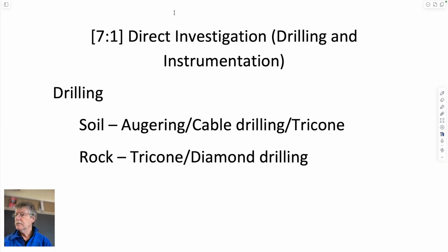They're preceded maybe by knowledge that you can get from what other people have applied at that site. But direct investigation would be digging trial pits, drilling holes in soil and drilling holes in rock, and maybe sampling. That gives you some point information about what's below you. And then being able to link that together by something that looks at something larger than a core, which is the size of your fist. It might be 100 meters long or 1,000 meters long in some cases, but something that only represents a very small part of your aquifer or subsurface, or aquiclude for that matter.